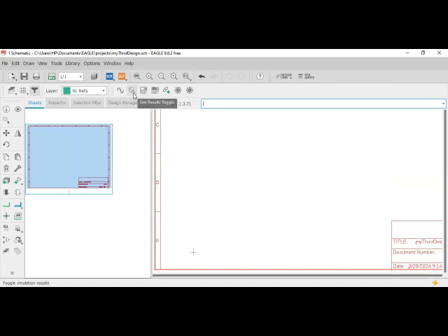Another important thing is the simulation result toggle, although we might not be working on this. But another important thing is the voltage probe. That is where we are going to use a probe. For example, if you are working with a multimeter, you have a probe, the positive and the negative. So for simulations, we need to add the voltage probe to any of the outputs or anywhere we want to simulate the voltage inputs or the voltage outputs.